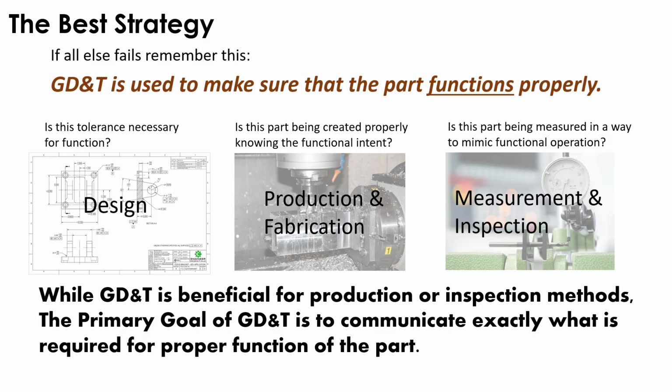Doesn't mean that you can't have notes hidden away, maybe even in the title block. You could have supporting documents that say anything that's shown to be coaxial is coaxial within this amount. What that truly relates back to, and you have to go back, is it a circular tolerance zone? Is it a square tolerance zone? How are you going to handle it? But simply put, you're wording out position tolerance from GD&T.